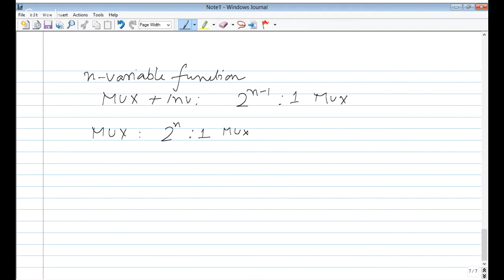Next is again from Naveen Kumar. The incandescent bulbs rated respectively as P1 and P2 for a specified operation mains are connected in series across the mains. And the power supplied by the mains to the two bulbs is, see, if power is given at a specified voltage, so resistance can be figured out as V square by P1 and resistance of 2 will be V square by P2. If current was specified, then power that I will use will be I square R. If voltage is specified, V square by R.